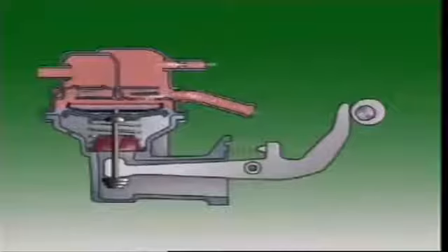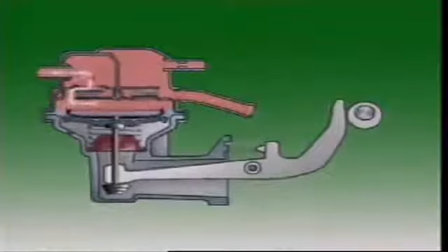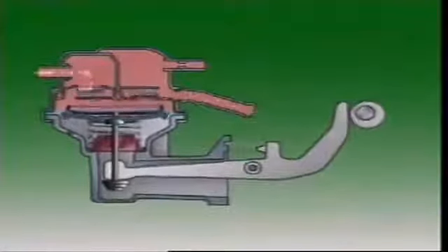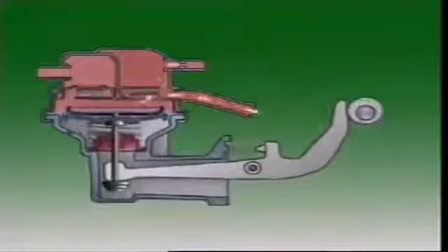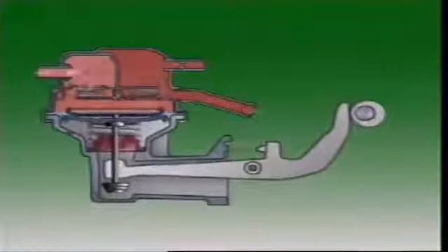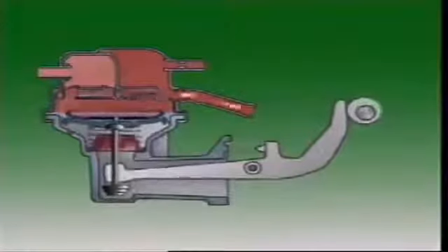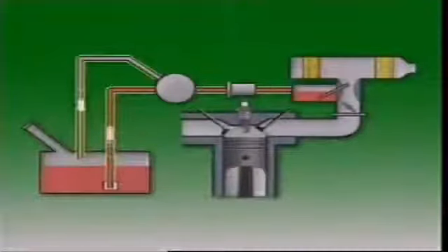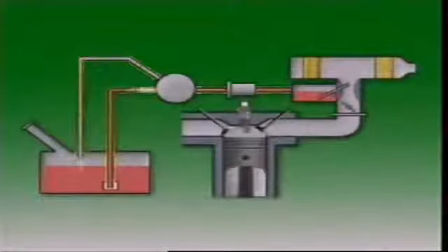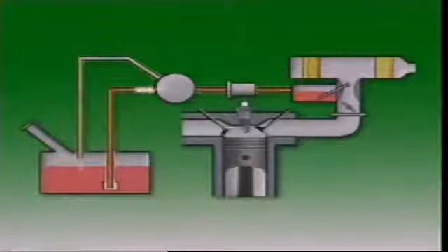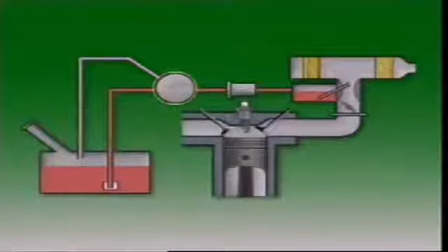into the carburetor. When the engine needs more fuel, the diaphragm moves through a long stroke to pump a lot of fuel. When less fuel is needed, pressure builds up in the fuel line to the carburetor and in the pumping chamber above the diaphragm. The diaphragm spring can't push the diaphragm up so far, and the pumping stroke is reduced. Some pumps also have a return line to send excess fuel back to the tank. As the fuel circulates, it cools the fuel pump and lines and reduces the chance of vapor locks.